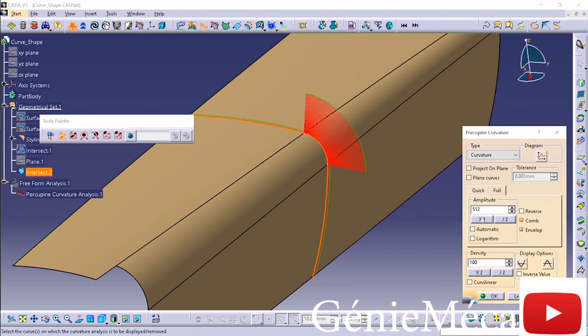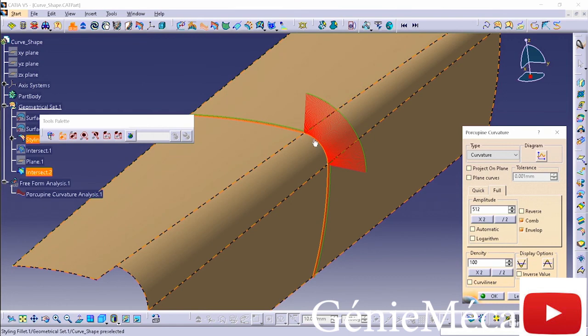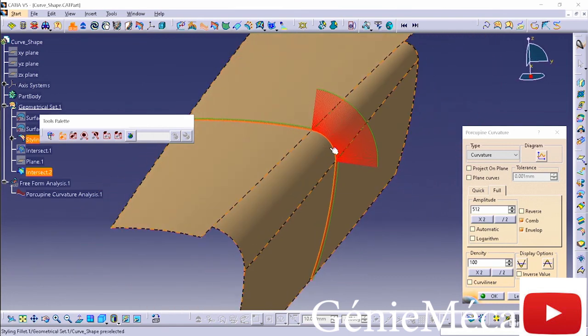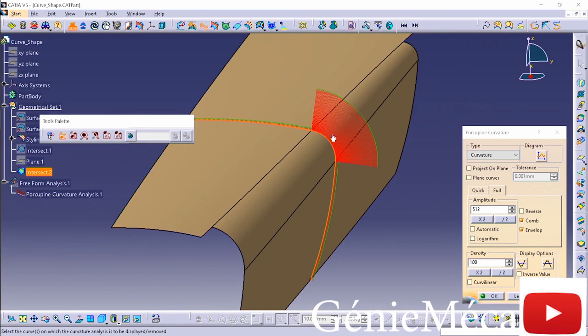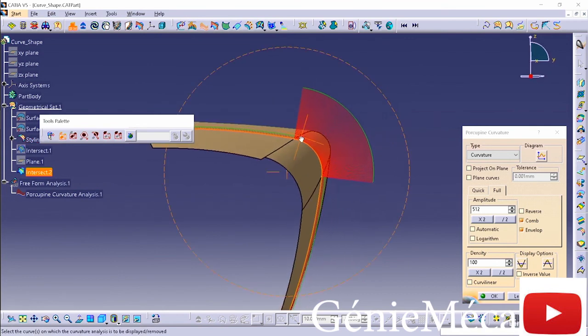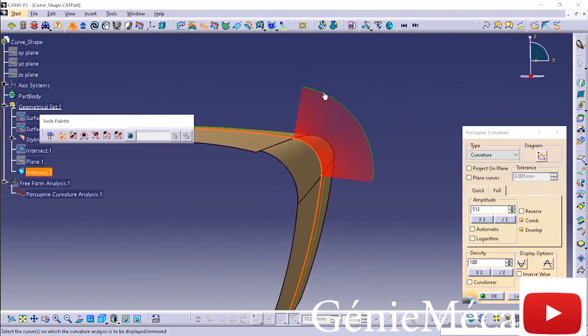So what's going to happen is if I'm measuring the radius, it's typically used for longer, broader, flatter curves. Maybe you're doing something across the hood of a car, something like that with big, long, broad strokes. Radius is really good to use for those types of curves. If you're using something with a lot tighter curvature, you may want to come in there and actually use a curvature graph like this to get a good indication of what's happening in the smaller, tighter areas. As you can see, I have a much larger exaggeration in the tighter radius. Now, again, back to continuities. The continuity is displayed by this envelope curve.